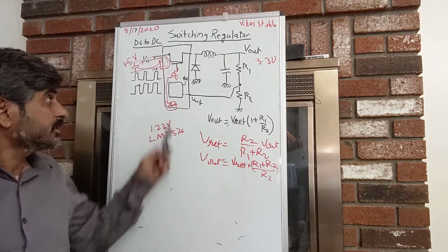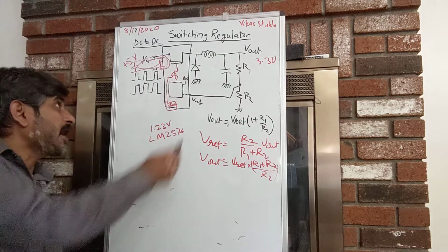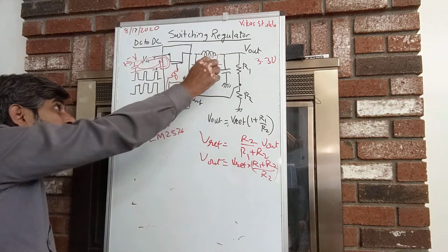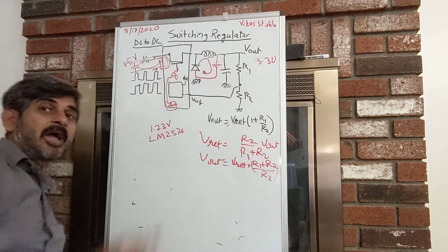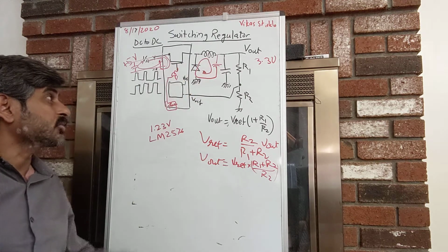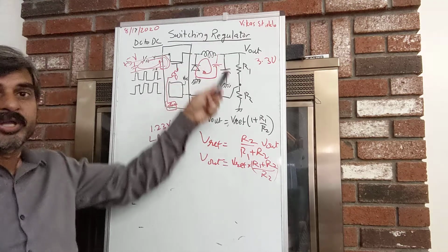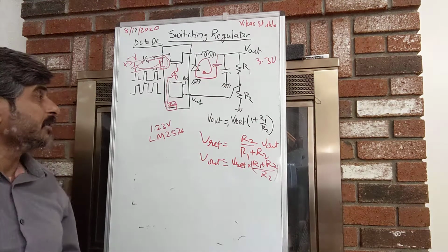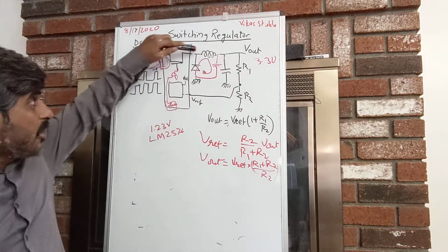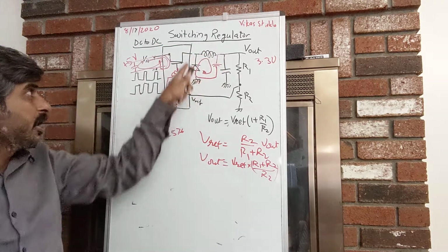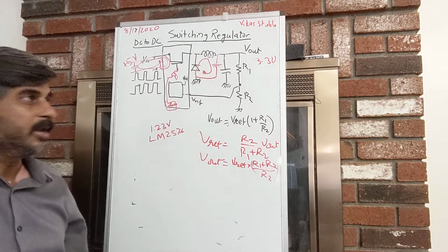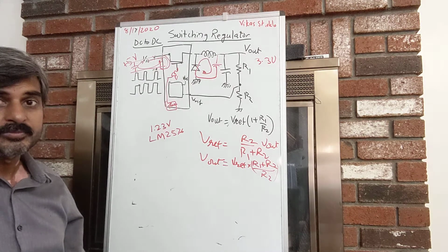In a similar fashion, on the output side, you should have a capacitor very close to it, because this whole loop could be radiating, and you want to keep one capacitor very close to this coil so that this loop area is minimized. This diode, for example, should be placed very close to this inductor to again minimize the loop area of radiation.